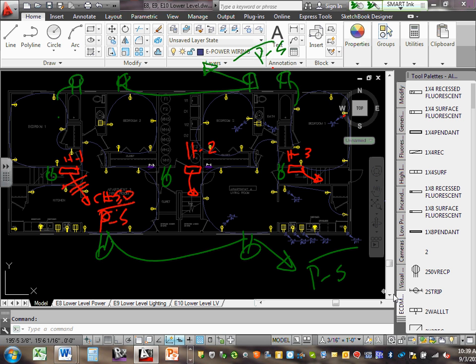These 3 receptacles, look how we circuit them. You don't have to show this, but they will be circuited like this to P-5. These are for the common, and at the top, Matthew, there will be another 3 receptacles circuited the same way. And remember, we can put 9 receptacles or less on one circuit? 20 amp circuit. Any comments, guys? Any questions?